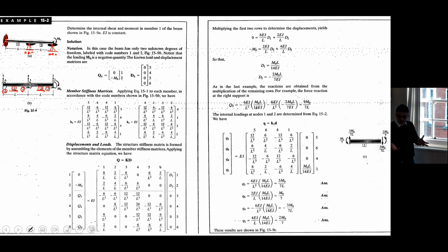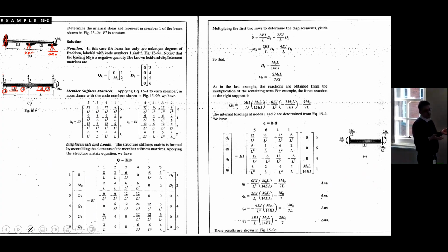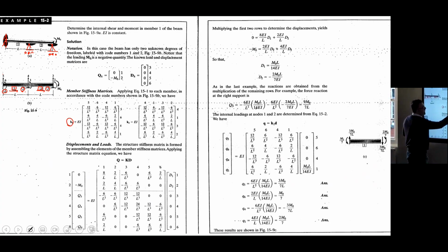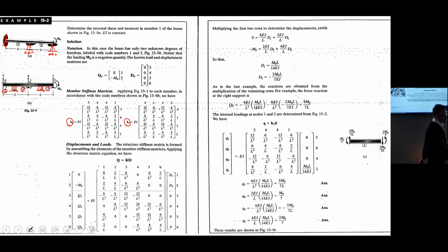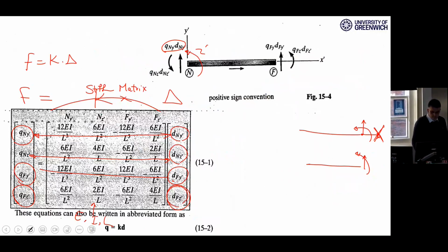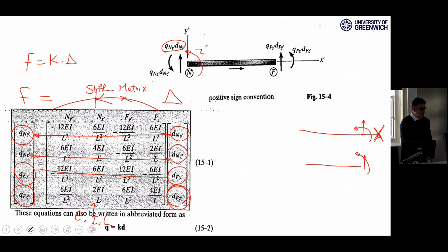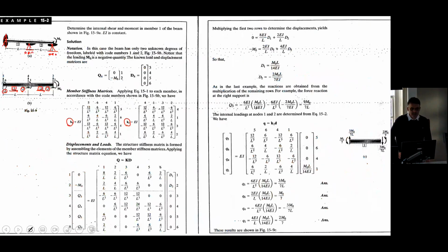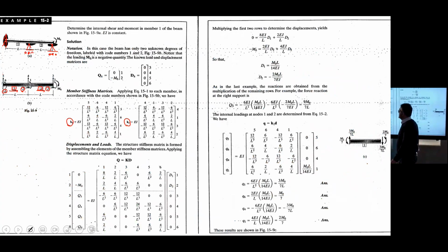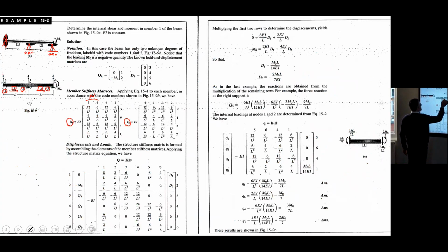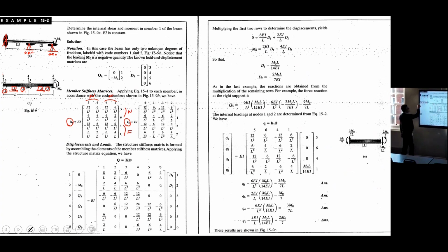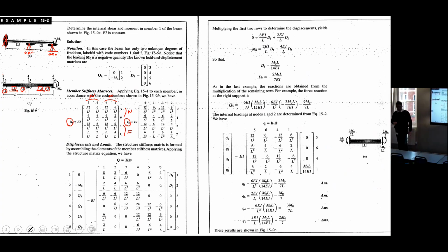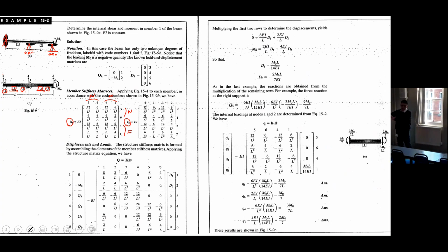So, again, we follow the same sequence as the previous one. We just assemble K1 and K2. Exactly, I'm filling with this formula. I'm using this 4x4 to fill that K1 and K2, right? These 2 are near end, these 2 are far end. Near end, far end. See, 6 and 5 are near end. Right? I'm just following that 4x4 matrix, filling here.